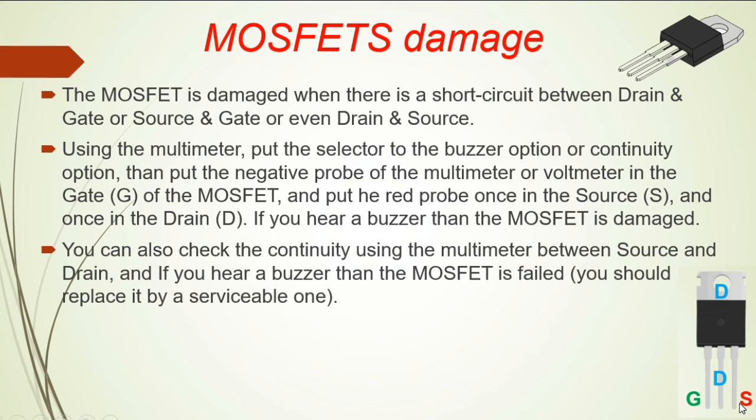If you hear a buzzer or a continuity, that means 100% the MOSFET has failed, you should replace it with another one with the same part number. Okay, the part number is always figured here in the MOSFET.